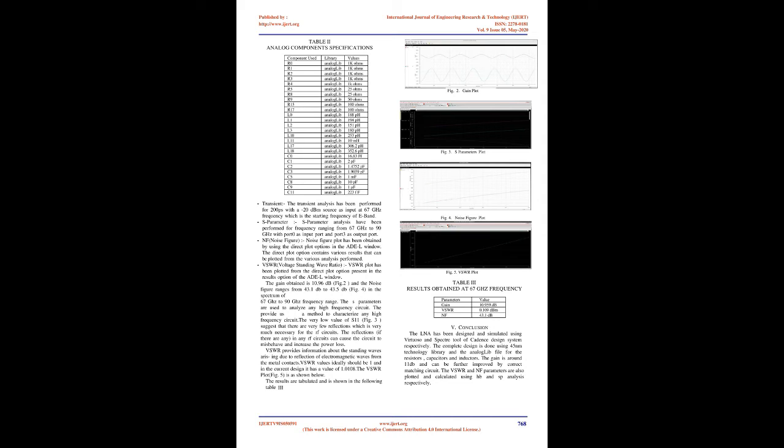The transistors NM0, NM2, and NM4 have larger width than usual in order to provide adequate current to drive the next stage. Whereas NM1 and NM3 have the usual 120 nanometers width to provide less resistance in the path. It is worth noting that this less resistance is required because they act as input resistance to a common gate amplifier. The stack structure behaves as a common gate amplifier.